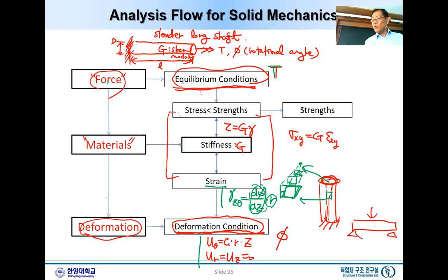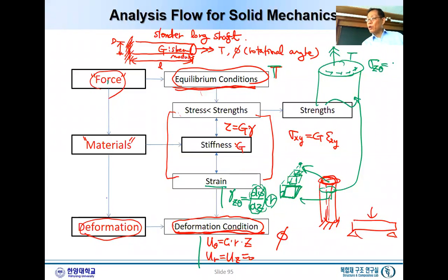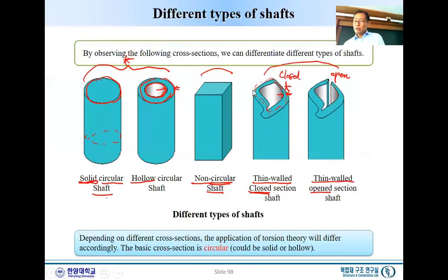How much stress will now I will draw a cross section, any cross section inside here, and this is subject to a torque. That is the external torque, and now this torque will generate a certain shear stress, which will be sigma, z, and theta. Simply we will call that tau, and there will be a tau stress generated by this torque. That is the equilibrium conditions. So that is the subject we will derive.